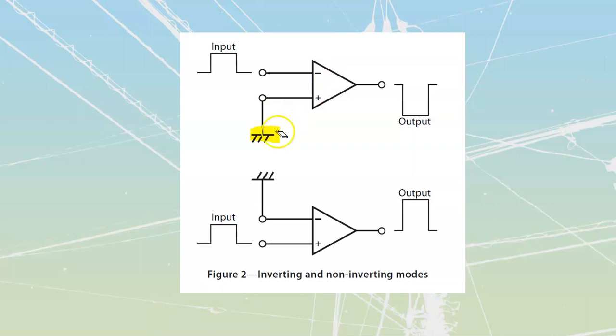Same with this other one down here on the bottom. We reference this one over here, so at 0 volts, that one is tied in at 0 volts. If my signal coming in is going positive and it's going on the non-inverting, I'm going to multiply it by a positive 200,000, my gain, which means it's going to switch out to my output in a positive direction over here.